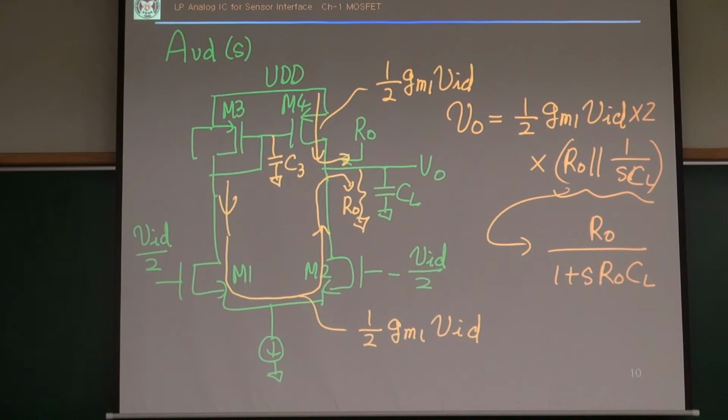We've seen two signal flow paths. One is a signal flow through here. This is the first signal flow. Second is a signal flow path through there. And then see, this is AC ground, so there is no capacitance involved here because that voltage never changes with time. However, this voltage changes with time. So, there is asymmetry. All right?